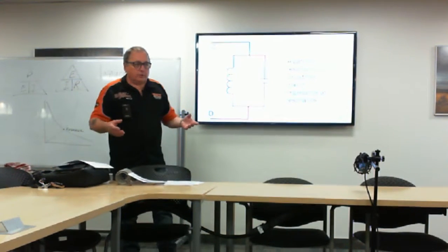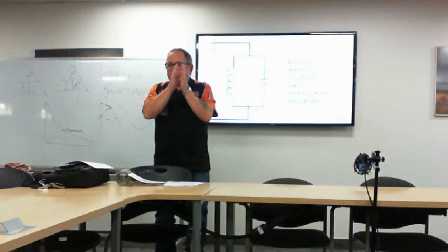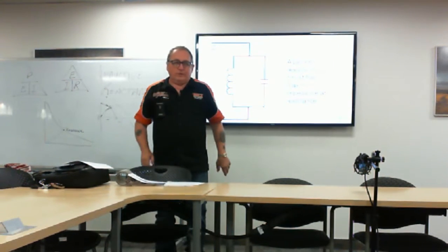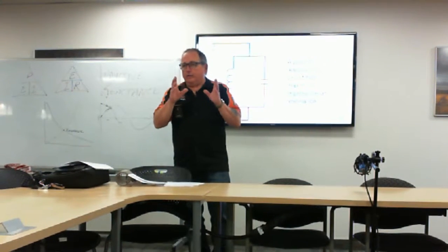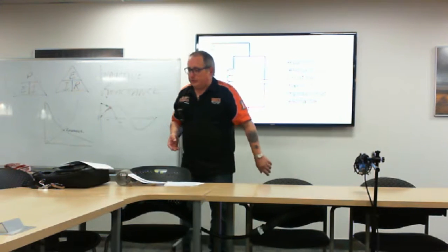No mechanical filter like this will give you just one frequency, because there are so many factors affecting it, like the temperature of the materials. So we make our filters fairly wide, and then we have other ways of getting rid of the noise.